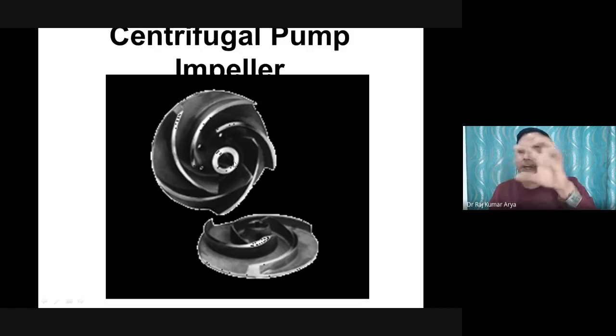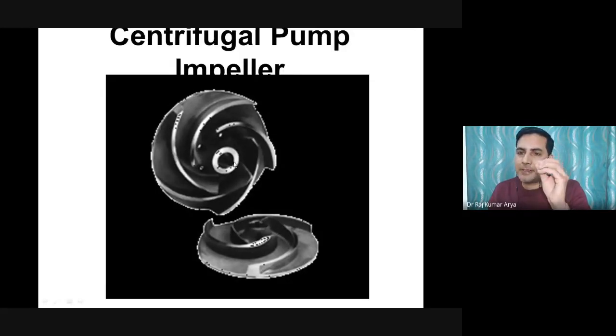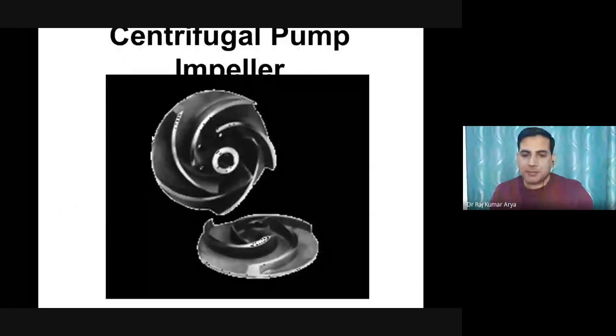Wherever the fluid moves at a high speed, the low pressure becomes lower than the vapor pressure of the flowing fluid, and it is converted to vapor. Once those vapor bubbles are formed, they collapse over a period of time when they move to a high pressure zone, and that pitting is the erosion. It's just like hammering of the impeller. So that is the cavitation part.